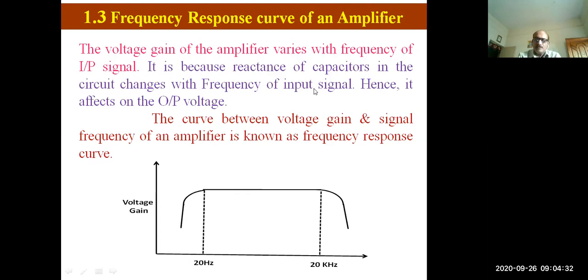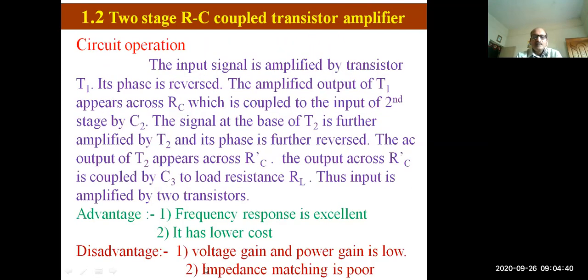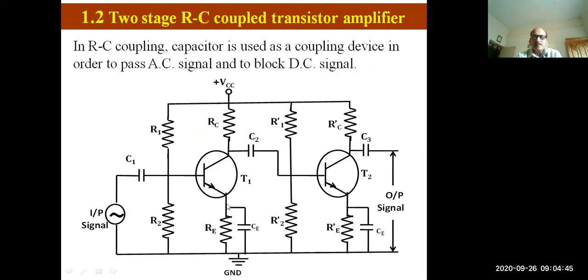Sir, you are only telling us, you are not showing us the diagram. Actually, how can we draw the circuit diagram of RC coupled amplifier? This is the voltage divider bias circuit of a single stage amplifier. This is the other stage voltage divider bias circuit. Here we have to draw the coupling capacitor, cascaded capacitor. We can draw the bypass capacitor across RE.